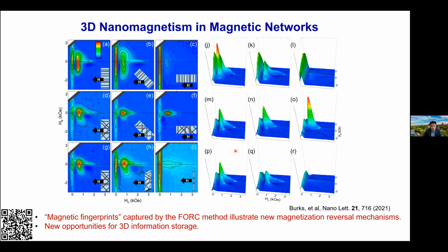And so we wanted to use the metal foam to see if we can develop some effective filtration materials. And this is in light of the challenges of the current filtration media. It turns out this 0.3 micron size range is the most challenging to filter. In fact, this is how the reference standards are made. N95 means they are at least 95% efficient at filtering out 0.3 micron particles. And the gold standard is the N95 masks.